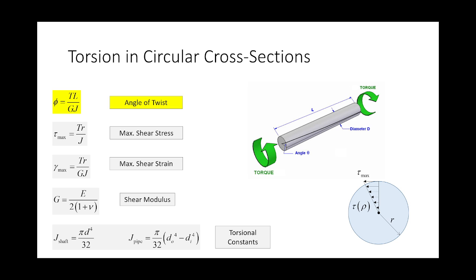So if I look at deformation, let's say before and after, let's say I draw a little point right here and I twist it, afterwards that point moves, right? And it has deformed. If I draw a dot right here, twist, it moves a little bit, right? But what about right here in the center? If I twist it, the center doesn't move, right? It rotates, but it doesn't move, right? Make sense? So I propose that from a stress standpoint, stress varies away from the center, okay?